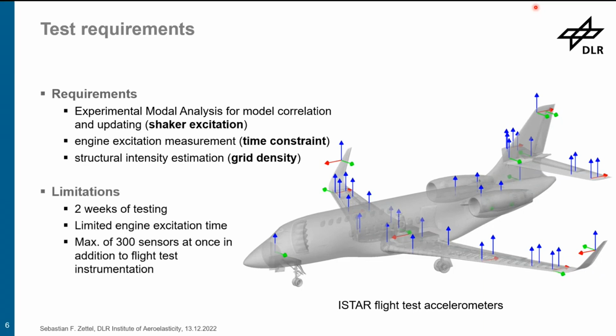Those were the requirements, and on the opposite we had the limitations which were given to us. There was only 2 weeks of time for testing for this whole measurement campaign, and as I already mentioned, the limited engine excitation time. And also we had 300 acceleration sensors available to measure as much as possible of the vibroacoustic behavior of the aircraft.